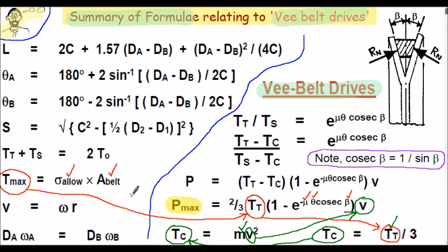And finally, the question wants us to determine the diameter of the pulley. So we could find the radius here, we could double that to find the diameter. We will know now the linear velocity V, we've calculated that to find the maximum power. We know the angular velocity in radians per second, that was essentially calculated from the information in the question. So that will allow us to find the radius, and then we can find the diameter. So that's my thinking step through the process here. Let's now undertake the calculations.